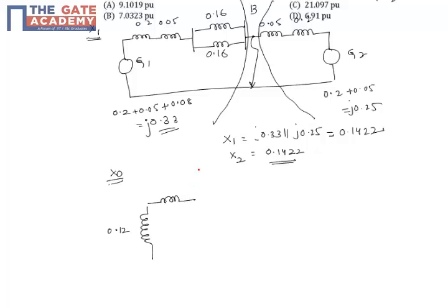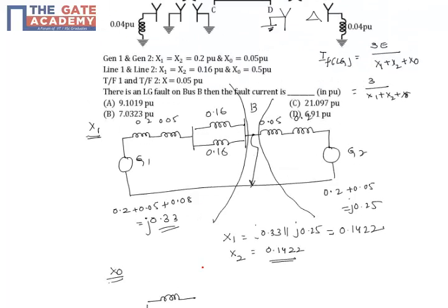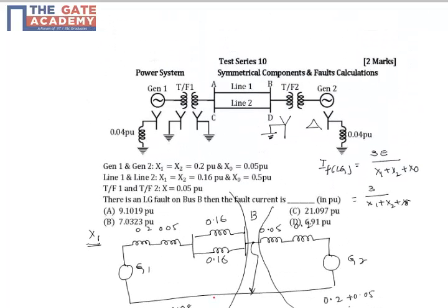Here I will show you how to draw the zero sequence impedance for this transformer. If you see here, this is a star on both sides, grounded. In this case only x0 will come, but in this case it is different, because generally while denoting the zero sequence, we will denote it like this, with series switches and parallel switches.